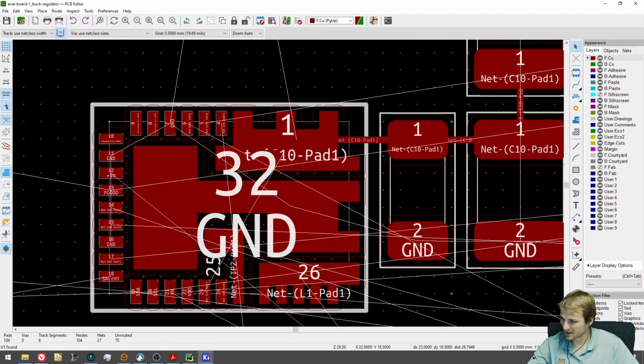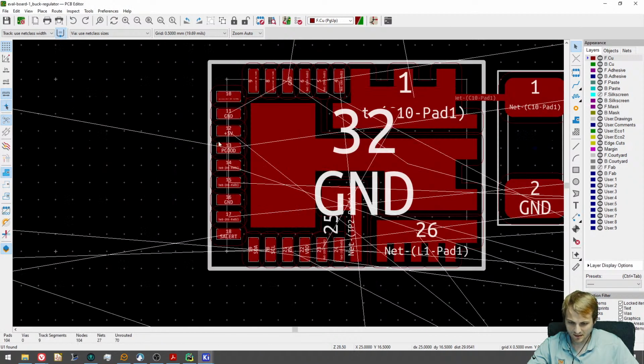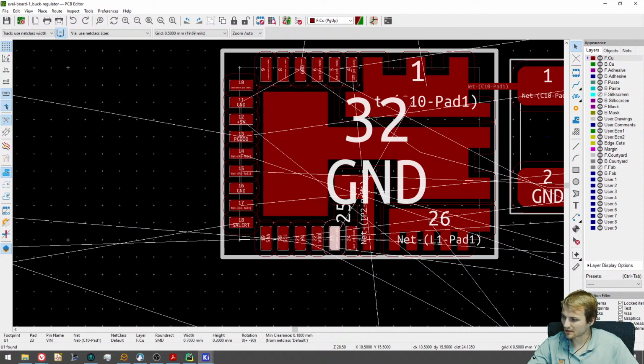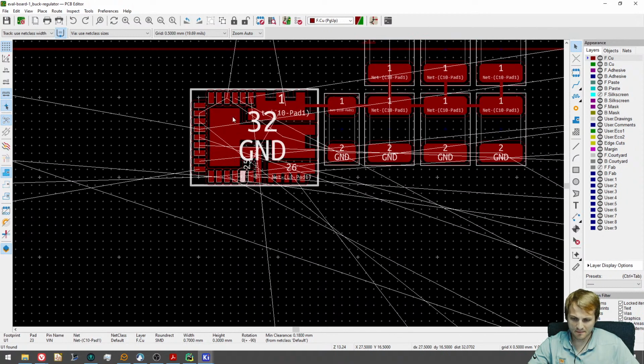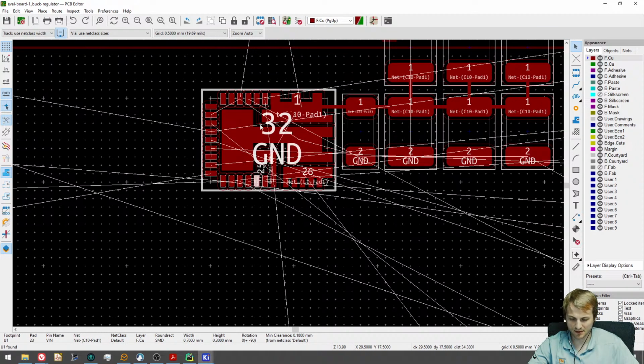Got it. So where is pin 23? 18, pin 23. Got it. Okay. Good to know. So you make VDD on top and ground to the bottom. If it's a two-layer, sure. I'm assuming with all these data lines, we're probably not going to be able to get away with it being two layers, but we'll see.